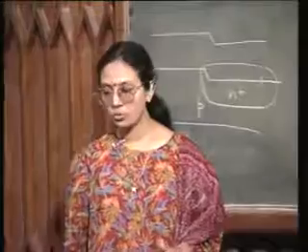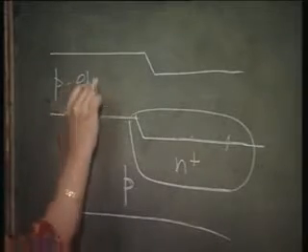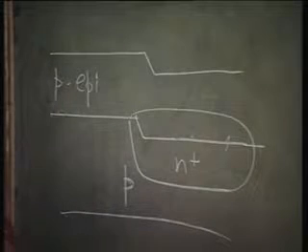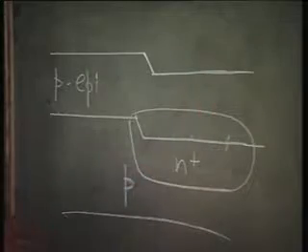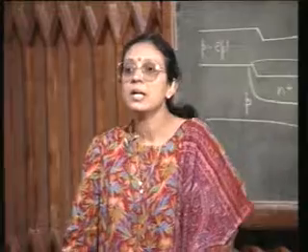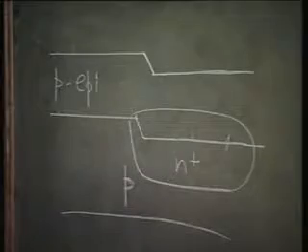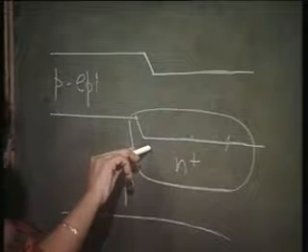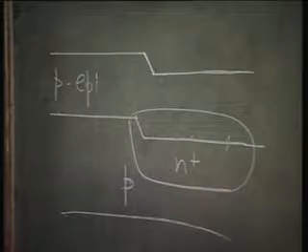Now, what do I want to do? Now, of course, I have to do my N well implantation, because you see this is also a P epi layer, and this indentation is going to serve to signify which is the region where the N well should be formed. This N well must be aligned to the underneath buried N plus region. Okay. So, that is all you have to do.